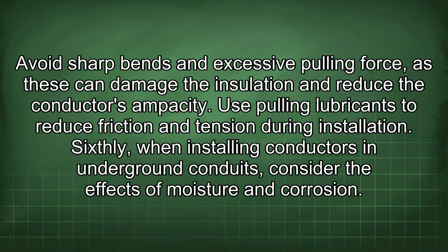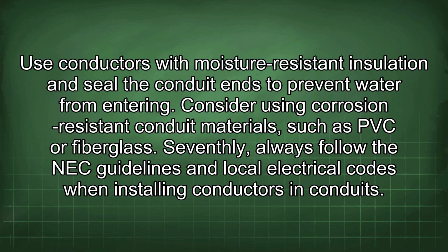Sixthly, when installing conductors in underground conduits, consider the effects of moisture and corrosion. Use conductors with moisture-resistant insulation and seal the conduit ends to prevent water from entering. Consider using corrosion-resistant conduit materials such as PVC or fiberglass.